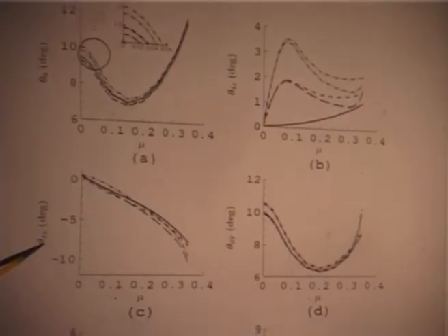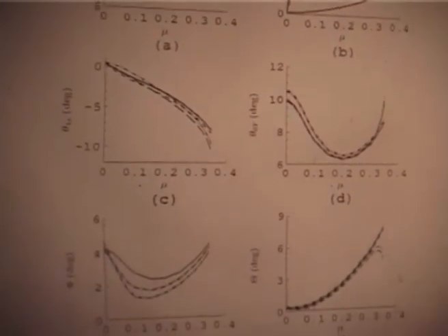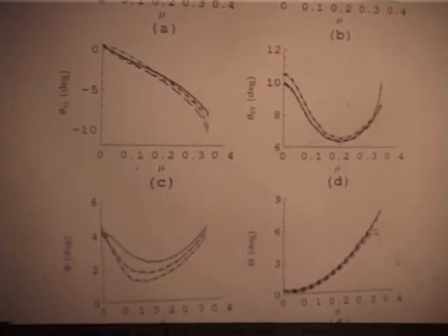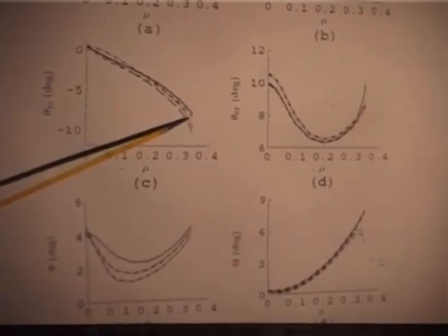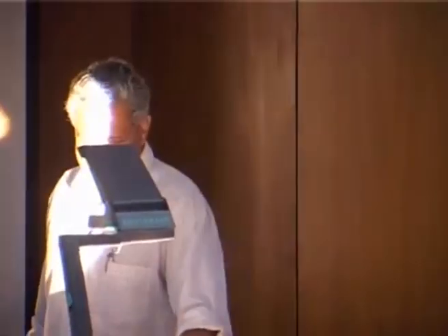Cyclic, that is theta 1s, which is directly related to beta 1c. They go up to minus 10, minus 20. So, the pitch angle can go to very high values in the retreating blade. Now, I just want to show this result, because this we also presented in the, this is published in the journal.